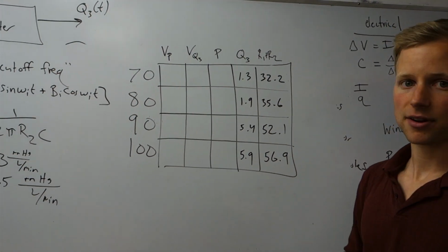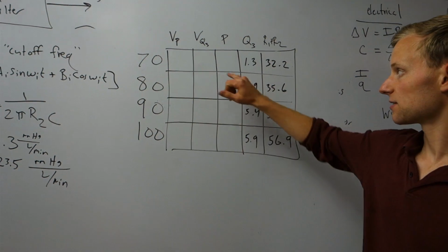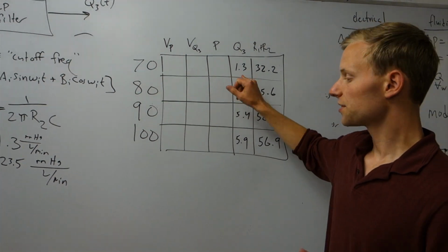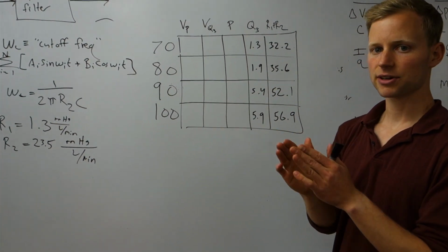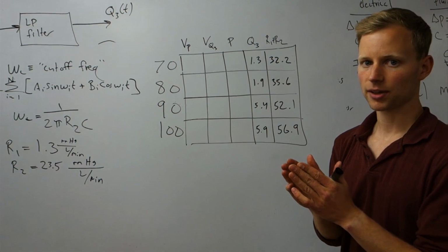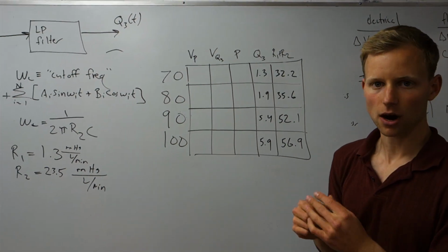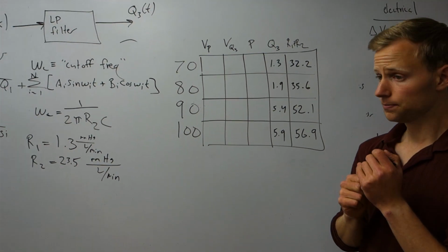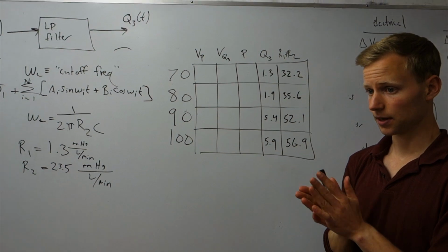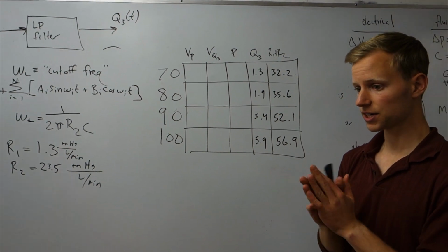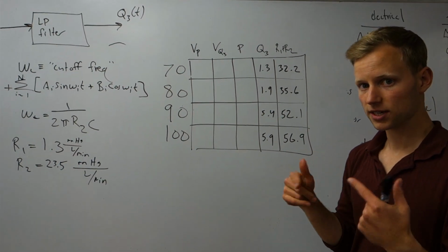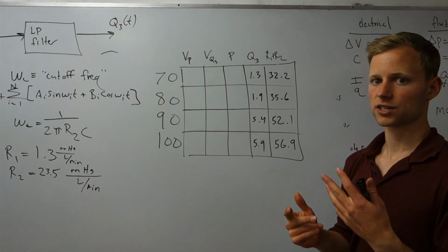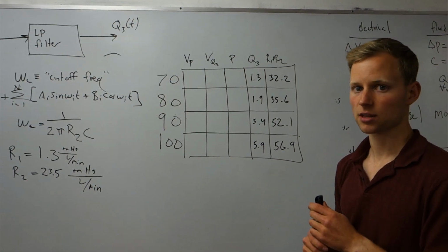But even if it is laminar in the vast majority of the pipes, even in this flow rate, there's still going to be exit and entrance regions where you can't simply use the delta P equals QR equation. Because when you have an expansion or contraction, you have induced vortices and eddies, and that causes a change in the viscous losses in the pipe.